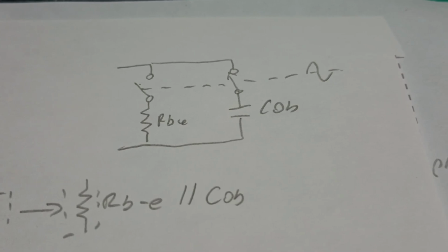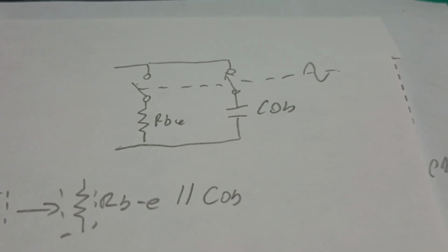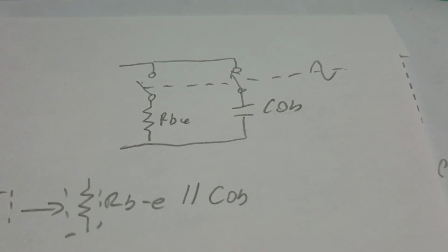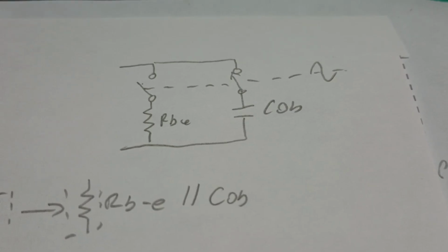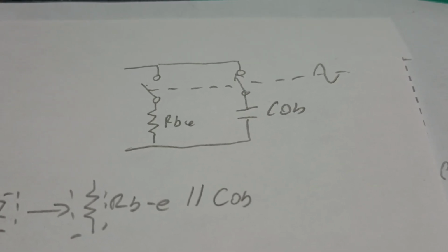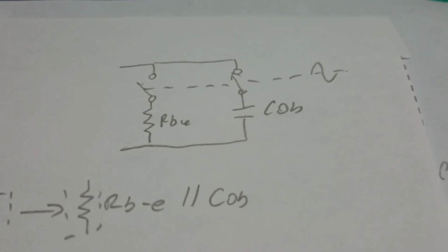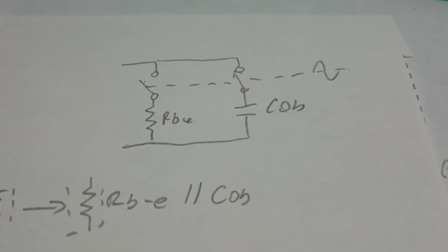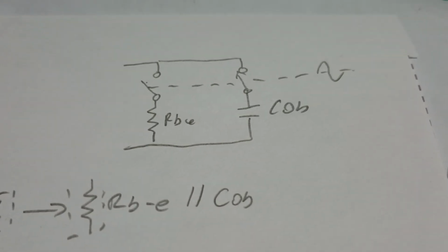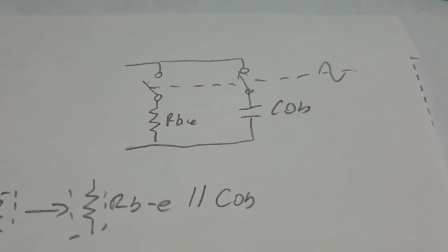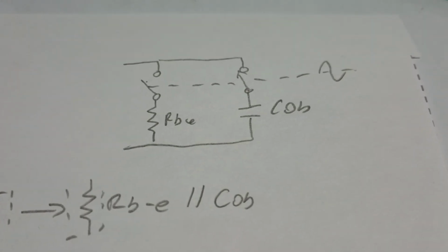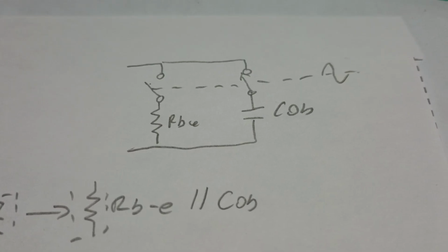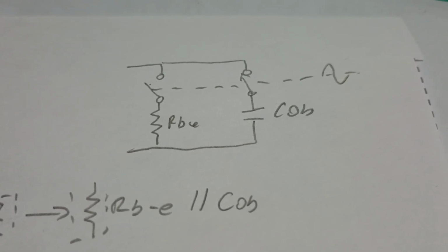How can that be in such a tiny semiconductor junction? Well, the capacitance formula is basically A area divided by D, and inside that transistor, the pieces of semiconductor have metalizations bonded to them. And those are the contacts between the leads and the pieces of silicon and junction. And those are capacitor plates. They're extremely tiny. You'd think there'd be no capacitance, but the thickness of those silicon areas is extremely tiny. Micrometers, thousandths of an inch, whatever.